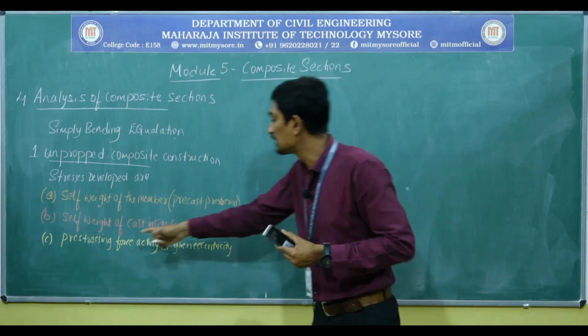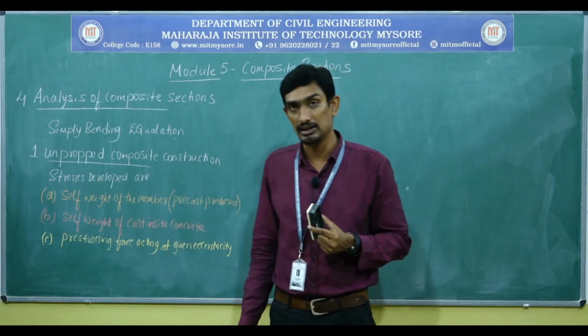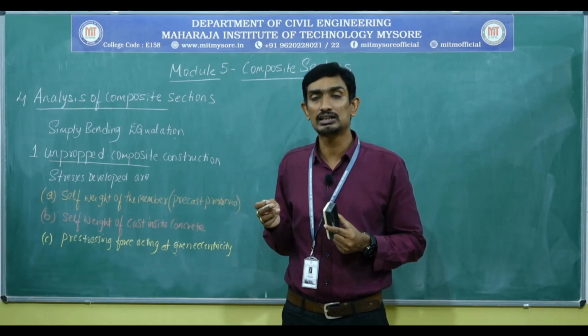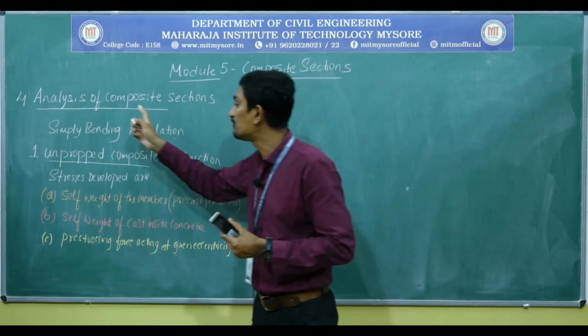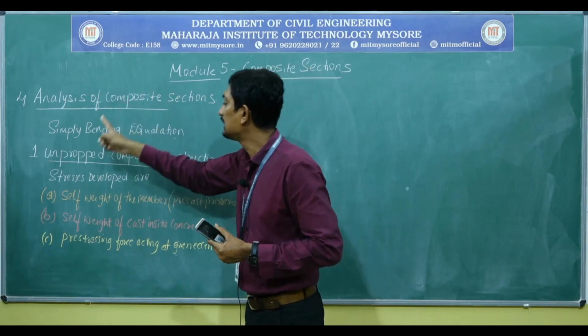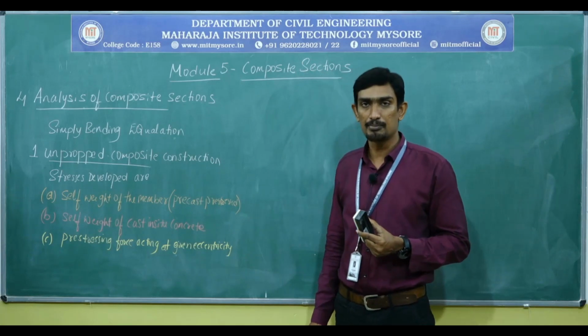So that is one more thing: pre-stressing force acting at a given eccentricity. These are the three things I need to consider in order to perform the analysis for the composite section under the unpropped construction case. Did you get my point?